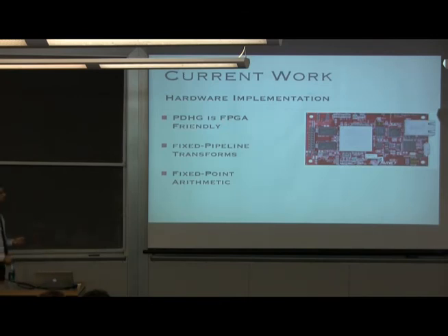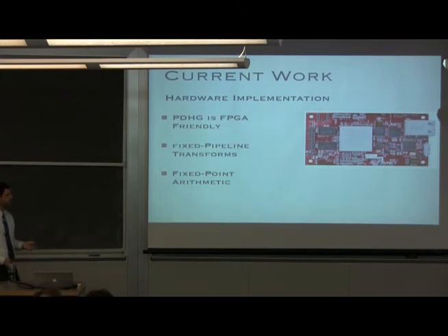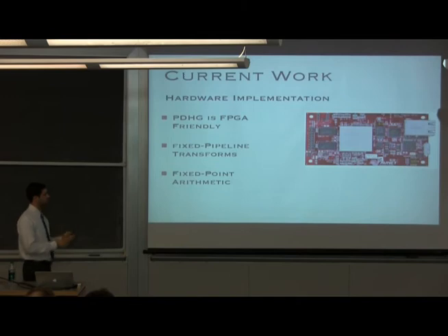On an FPGA, you have a very limited number of gates to work with, and you actually have to build a hardware implementation of every step in the algorithm. If you have a very long, convoluted algorithm, then you very quickly run out of gates on the device. But by choosing something that's parallelizable and has a very small footprint, you can fit a lot on these FPGAs. But there's some changes you have to make to the algorithms to make them hardware friendly.